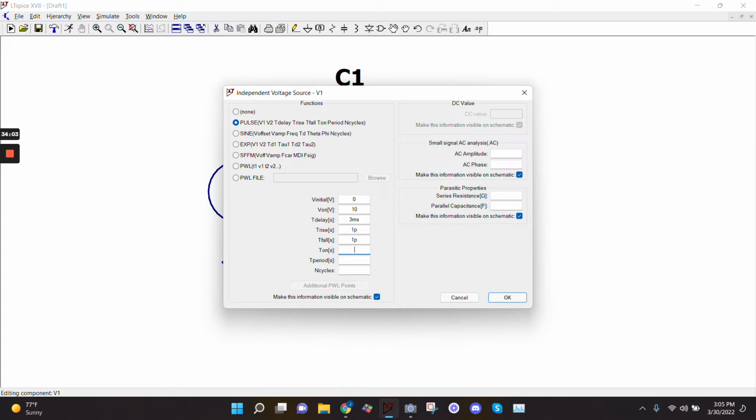Because typical supplies, and when you have bits moving around inside of electronics, and you have function generators that generate these signals, it'll say in the manual somewhere that the rise time is between 20 and 40 picoseconds. It's a ridiculously fast rise time. I just put 1 pico because it's easier than typing 20 or 40.